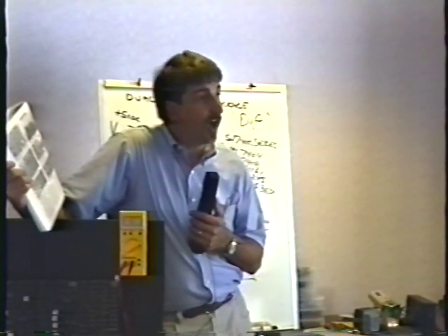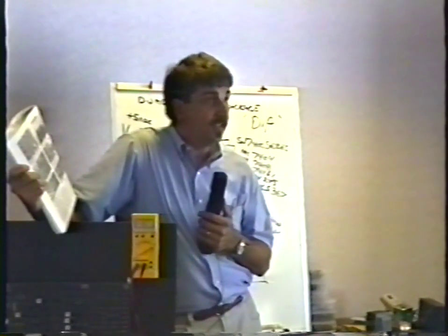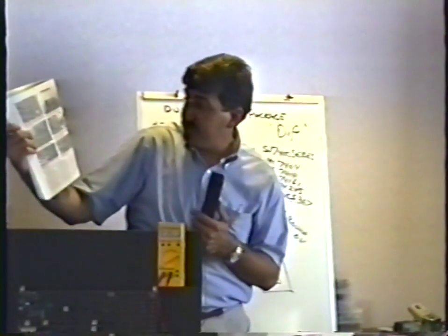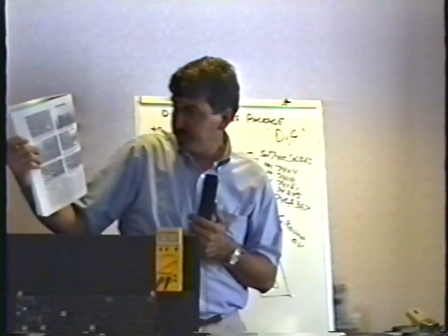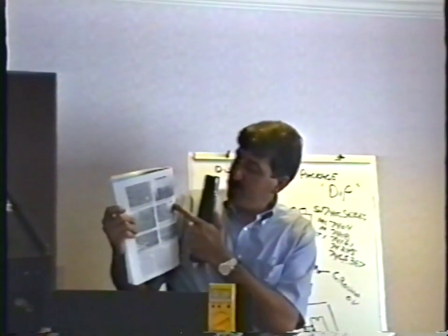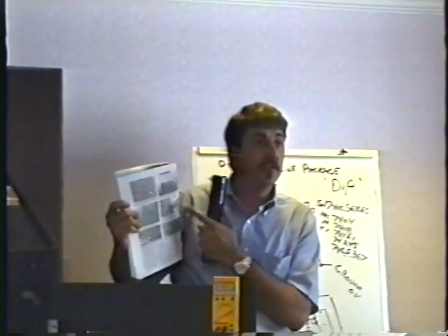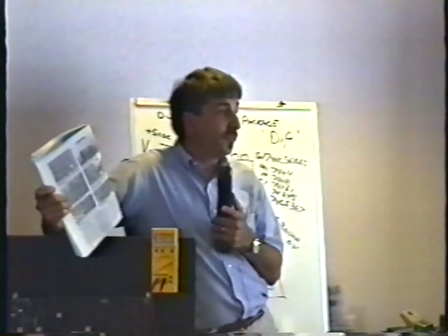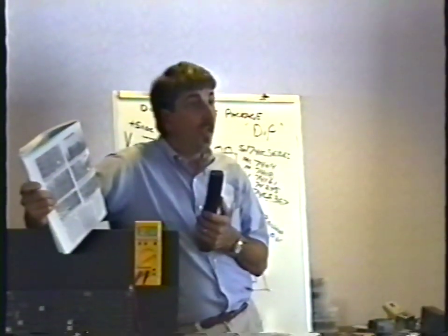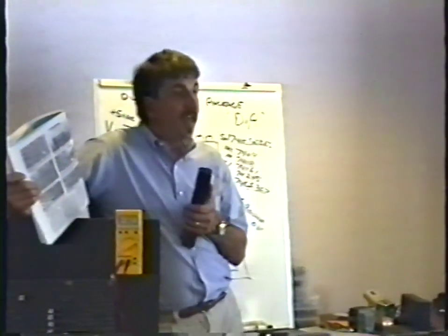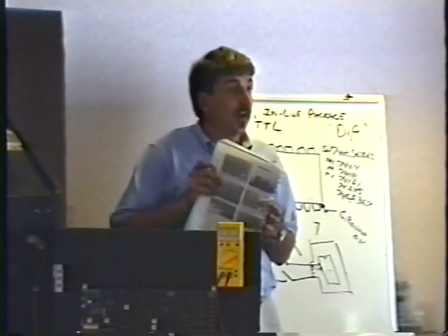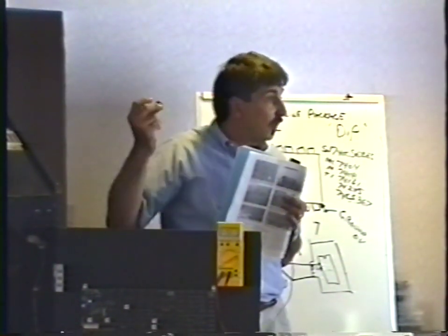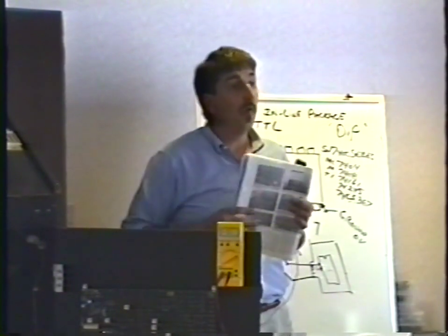You cut all the legs off the IC. In other words, you cut the body of the IC off, just leaving the legs, as you see in figure 4, sticking out. Then one at a time, you use your soldering iron to lift the pins off the board. You pull the pins off one at a time, then you use your solder sucker to suck the solder out of the holes, stick the new chip in, and away you go.